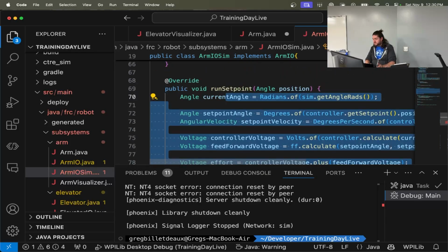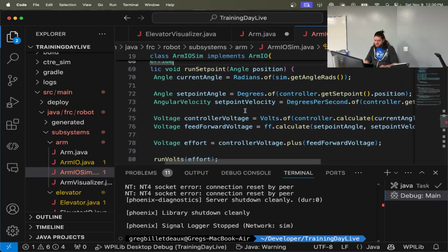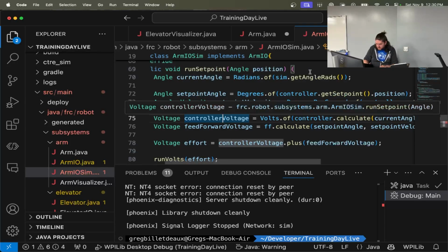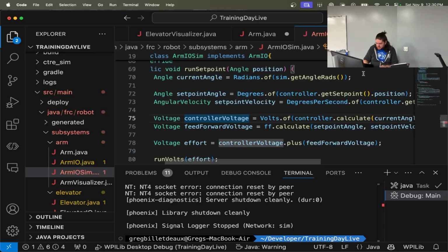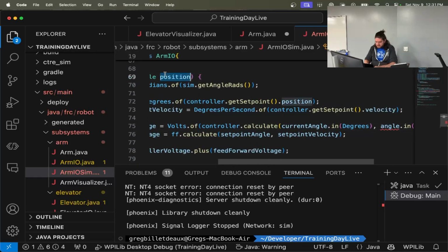They can be written during the preseason if you want to do them. And then, yeah, now I have that set point, which takes a current angle and a set point angle, feeds it into a velocity, feeds it into a controller, and I'm going to double check that it looks right, because I remember during my practice run through, this had an issue, but I also had set the gearing to 4 instead of 75, so it was really struggling to do anything, so that probably was the issue. Set point, set point. Oh, there we go. That's because of this.